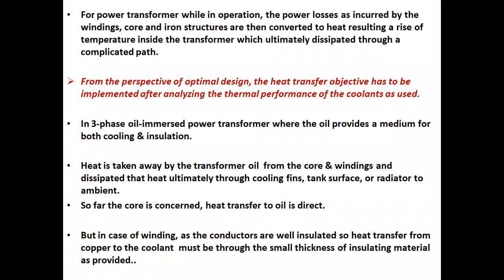For a power transformer, while in operation, the power losses incurred by the windings, core, and iron structures are converted to heat, resulting in a rise of temperature inside the transformer, which is ultimately dissipated through a complicated path. From the perspective of optimal design, the heat transfer objective has to be implemented after analyzing the thermal performance of the coolants used.